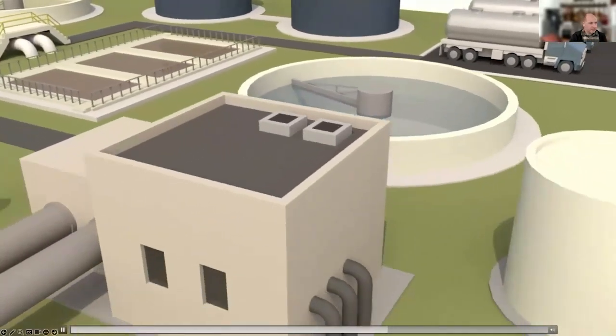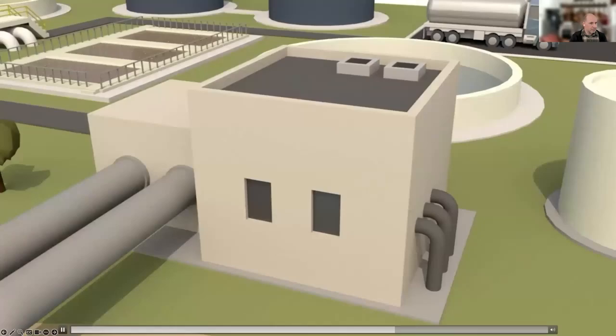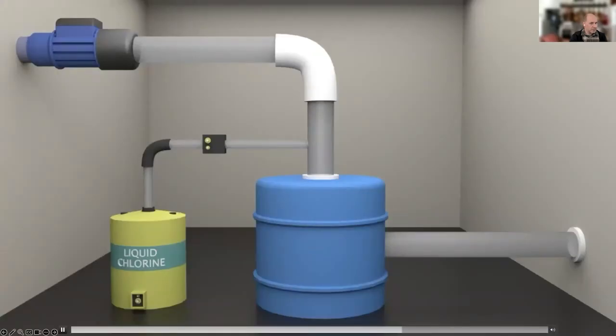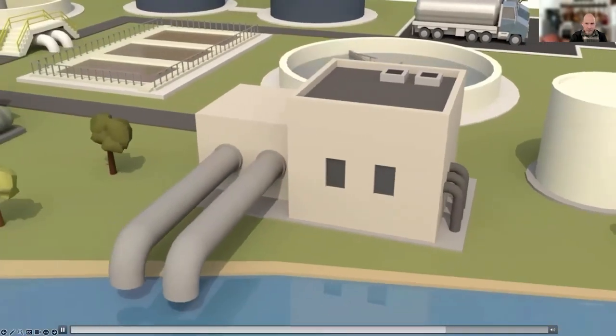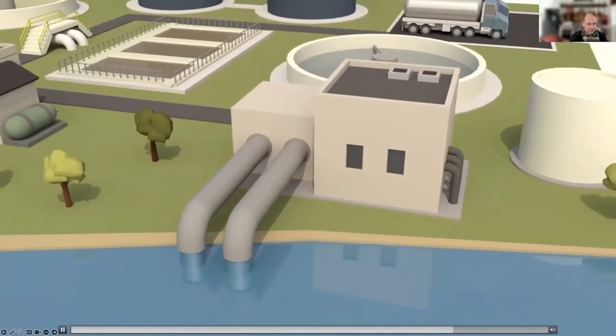Next begins chlorination and chemical treatment. Wastewater contains many human-centric organisms that are associated with various waterborne diseases. Chlorine is added to the water to selectively destroy any disease-causing organisms in the water. Some treatment plants add an additional chemical to the water to remove any remaining chlorine prior to discharge. This dechlorination protects fish and other aquatic life.